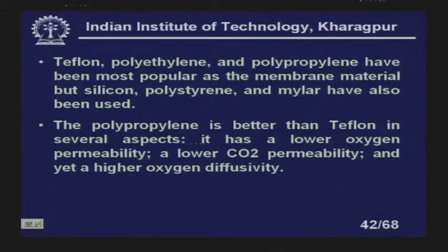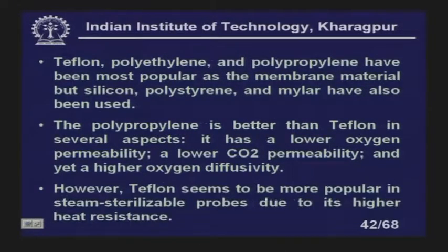The polypropylene is better than the Teflon in several aspects. It has a lower oxygen permeability, a lower carbon dioxide permeability, and yet a higher oxygen diffusivity. However, Teflon seems to be more popular in steam sterilizable probes due to the higher heat resistance that I told you earlier. So, this is a property which it must have.